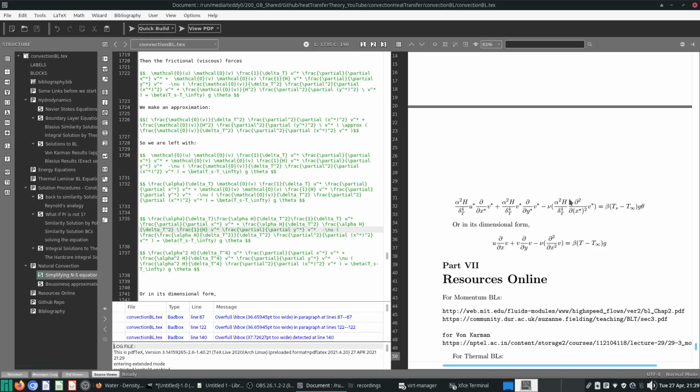The only thing is that unless this nu is so small, which means we have an inviscid flow, we cannot ignore it. For the most part, we consider most flows to have some sort of viscosity. In fact, since we are talking about laminar flow, the viscous forces will be quite significant, so we can never ignore that.